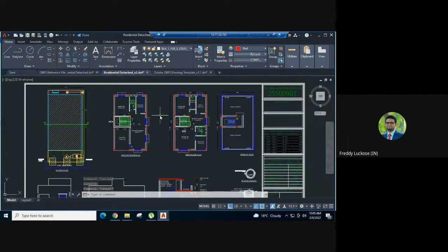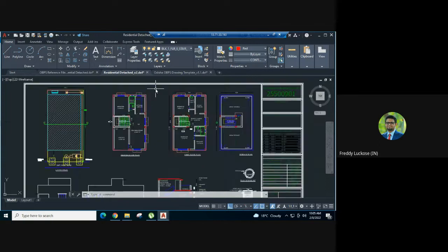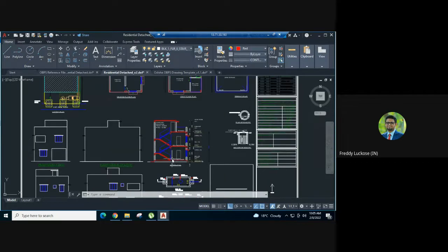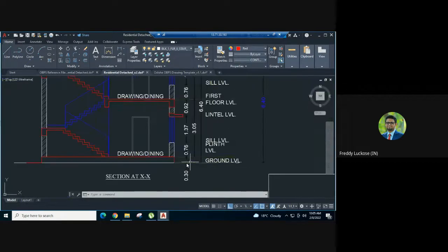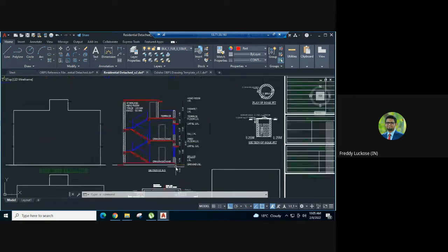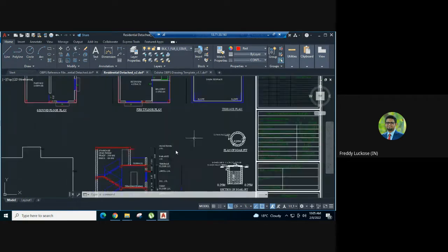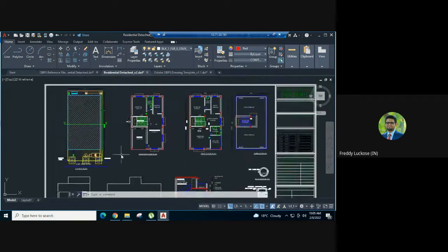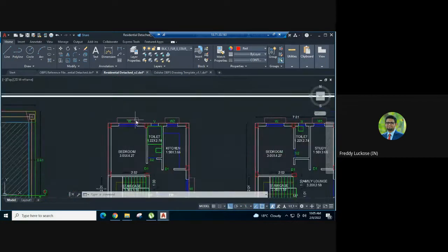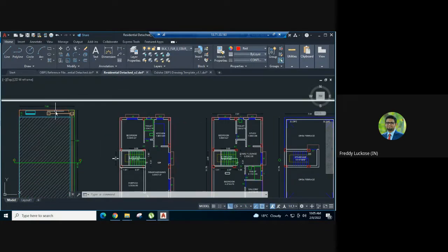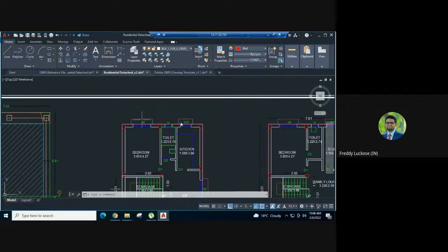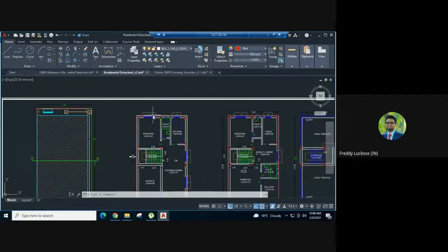Okay. So before moving ahead, we can also make some of the provisions that are coming inside a project that are according to our design. For example, our project has a plinth, so we can denote the plinth height here. We have parapet, mumty, and we also have these chhajjas that are falling on the setback. So let's cover these points as well, and after that we'll scrutinize the drawing.